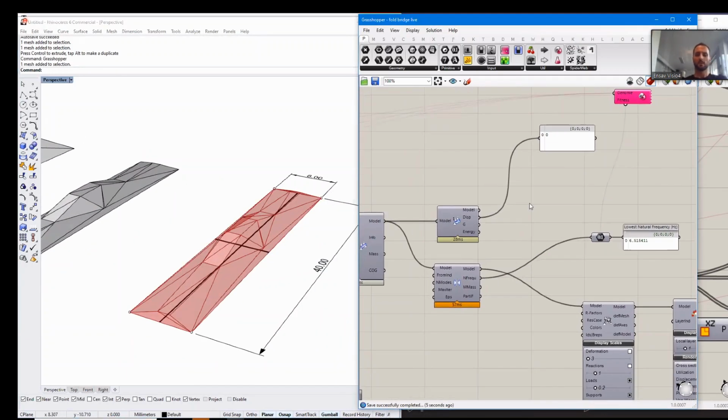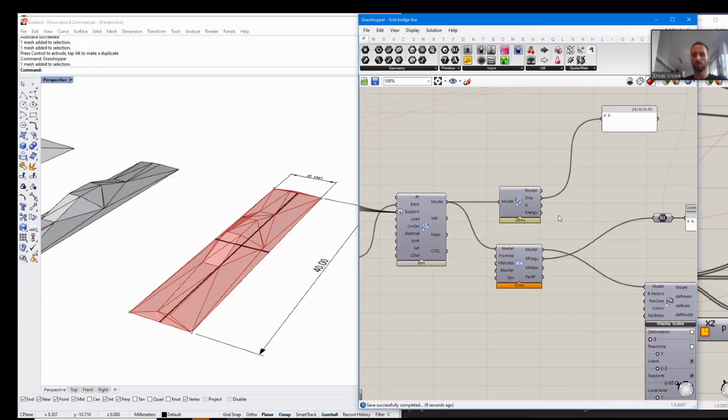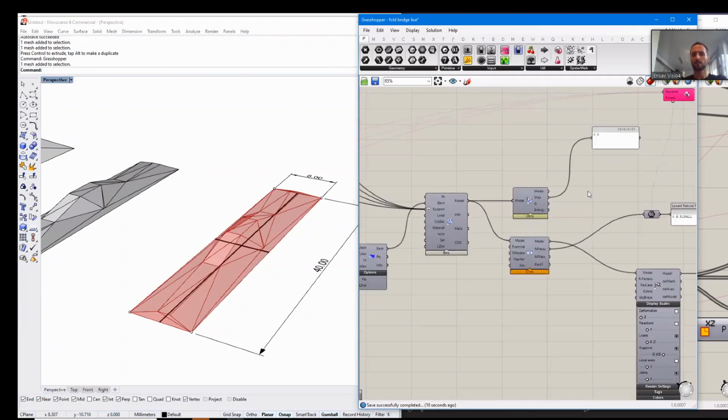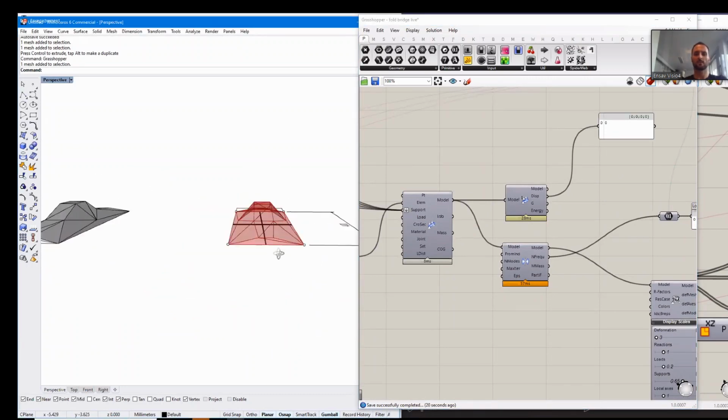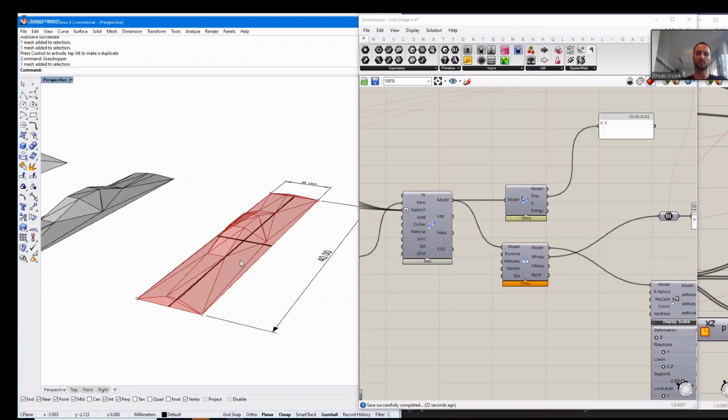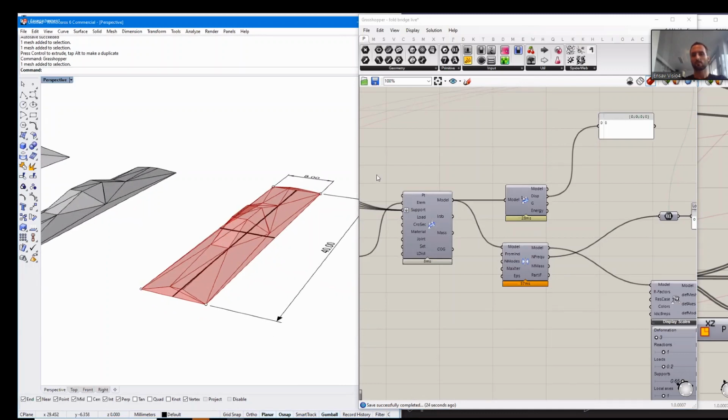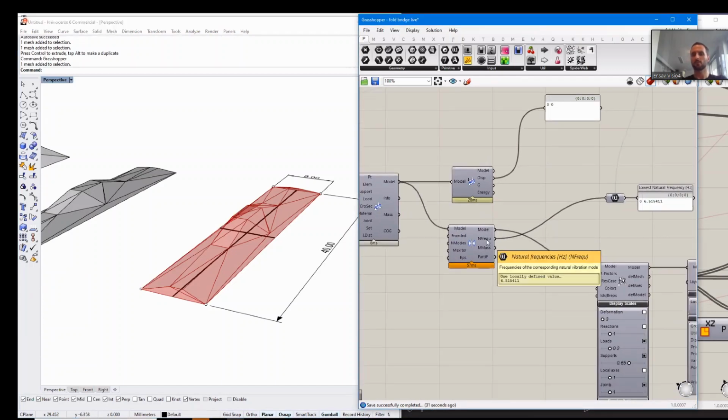For this now, we are going to define a second goal and a third goal. So the second goal will just be the displacement, minimizing the displacement value, and also minimizing the surface area of the bridge design. So these goal values, minimizing the displacement and maximizing the lowest natural frequency, go in the same direction of making the structure stiffer.